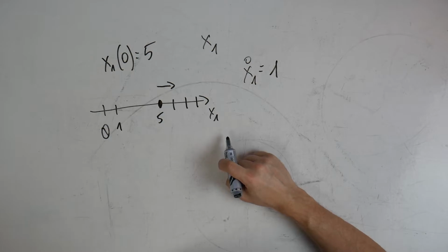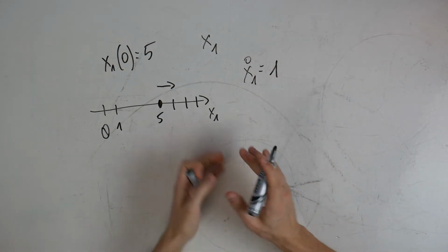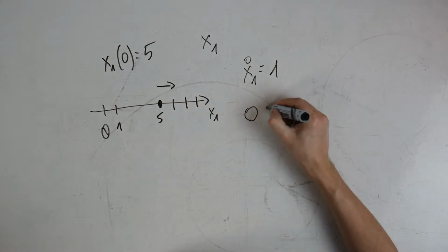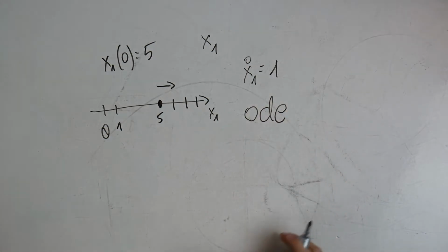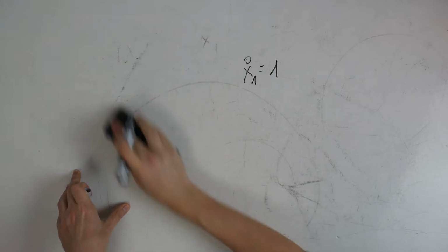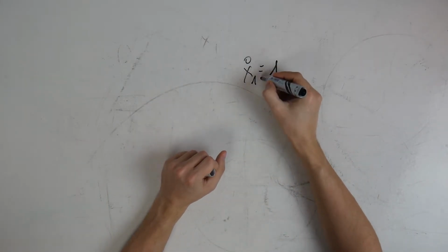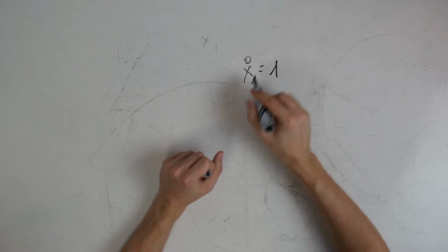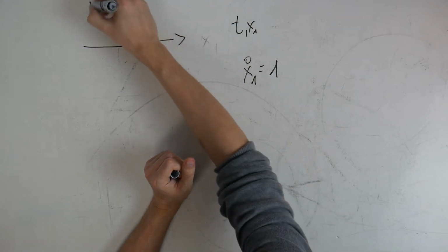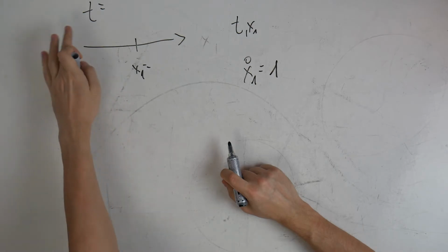How do I make a simulation like that? Well, this is a first order differential equation, so I can actually just solve it like an ordinary differential equation. So in Matlab, I need to create just this function. So I need to create a function that calculates based on time and x1, because this is what I'm given usually at my picture, the time, current time.